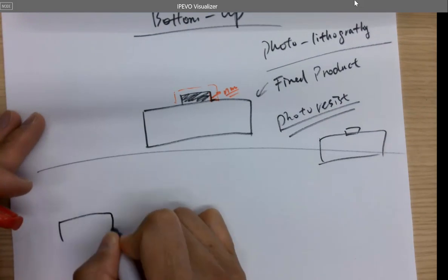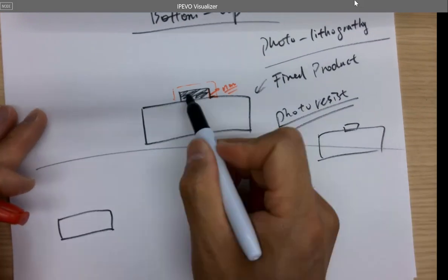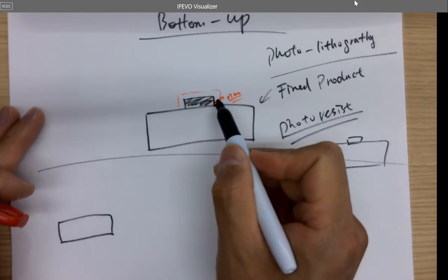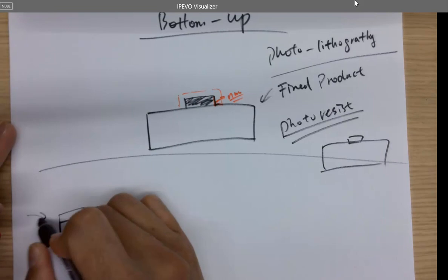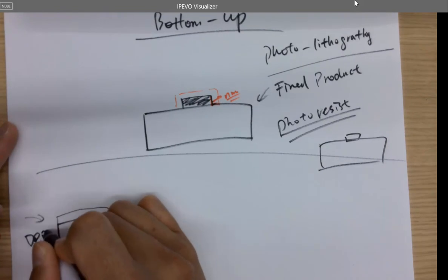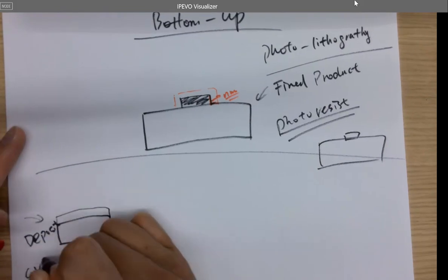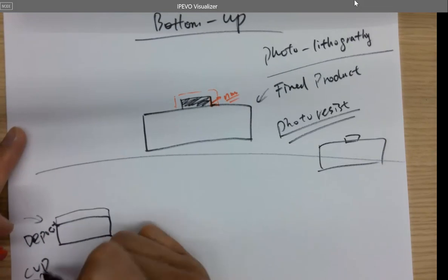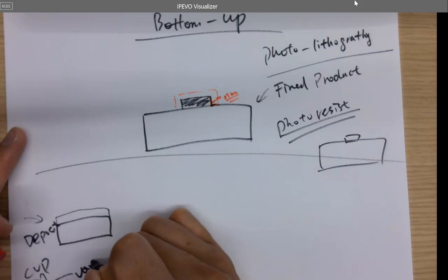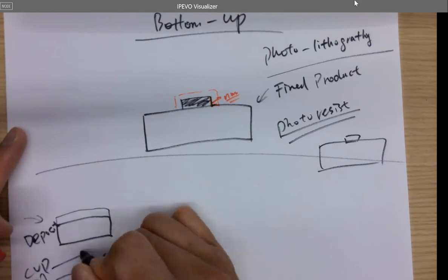So we grab a wafer, right? We know we need a metal layer on the top. So at the very beginning, we just spin, no, it's not spin coat, it's deposit. You can use CVD, chemical vapor deposition.